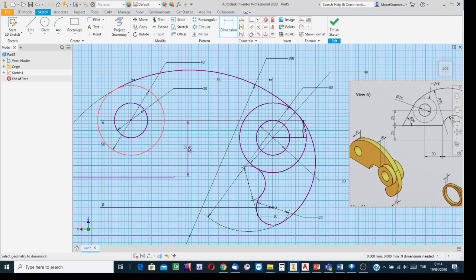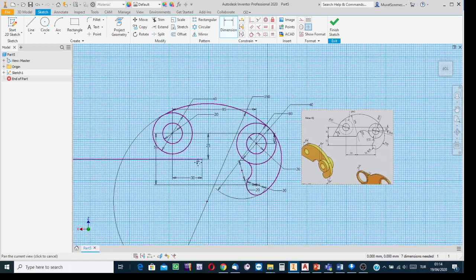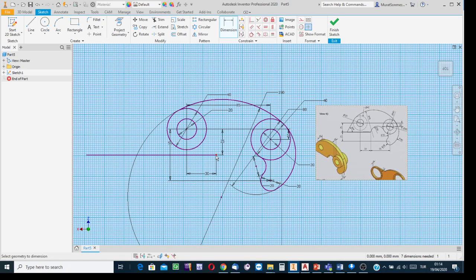While in this direction, move the cursor and click, and into this box write the constraint. In the vertical direction, the coordinate of the point is 25. Then, indicating the circle, indicate the terminal point of this line. In the horizontal direction, its coordinate is 30 relative to the center of the circle. Okay, then the line is in the correct inclination and its terminal point is at the correct place.